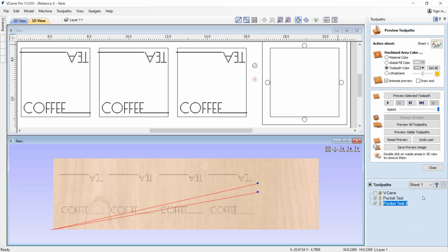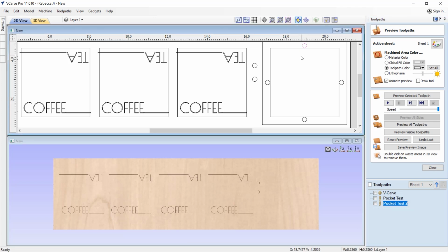And so the idea is we're going to run these toolpaths on our CNC, so we're going to run both of the pockets, and then we're going to take our pin and check which setting actually fits best, and whatever fits best we're going to apply it to the actual pockets for our pins. So I'm going to take a good guess here, and I'm going to say that the one with the allowance is going to work best for us, as we're going to allow for a little bit of wiggle room for our pin to slot in.